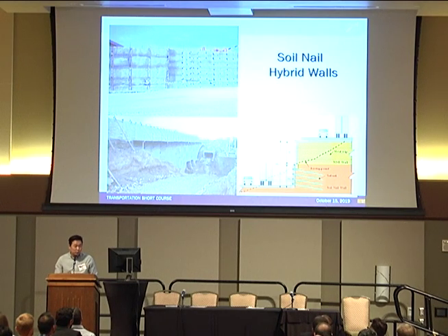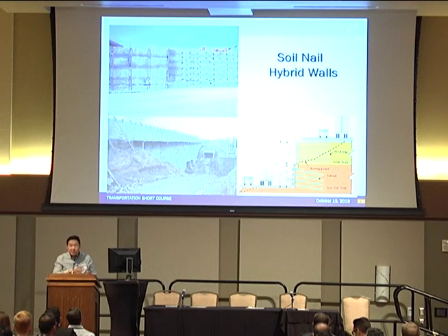The other option is to set the MSE wall with a 2 or 3 foot offset at the interface between the fill and the cut. This 2 or 3 foot interface can be used as a flume to handle the drainage from the retaining wall. These two options are viable, but we do not recommend a fill wall on top of a soil nail wall with a continuous face.